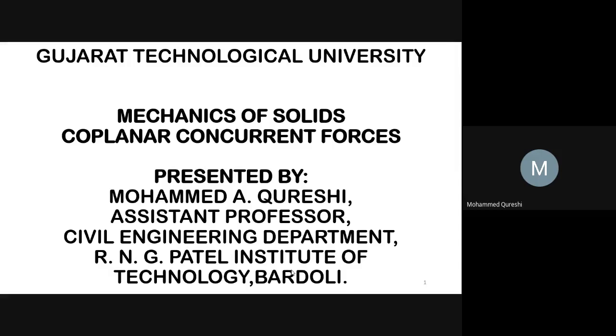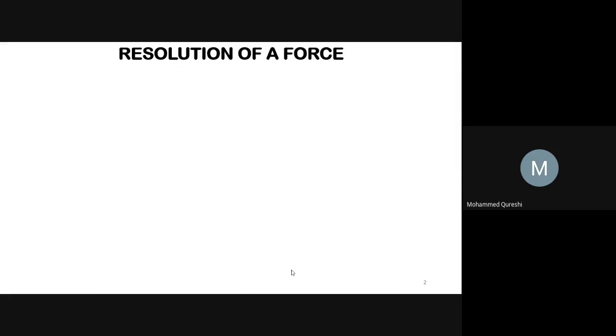We had also studied force, characteristics of force, and system of forces. Also, in the previous lecture, we had gone through parallelogram law of forces and its examples. Now, we will study coplanar concurrent forces. In that, we will go through resolution of a force. So, what do you mean by resolution of a force? It is nothing but a process of splitting up the given force into two or more components in a particular direction without changing the effect on the body.